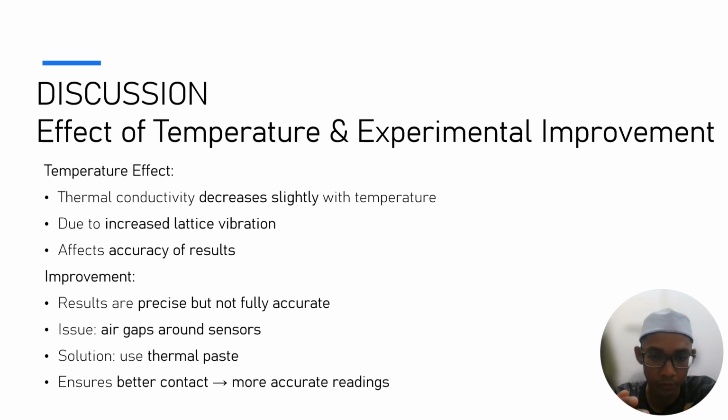Although our results are precise, they are not fully accurate. One improvement is to apply thermal paste at the sensor contact points to eliminate air gaps and obtain more accurate temperature readings.